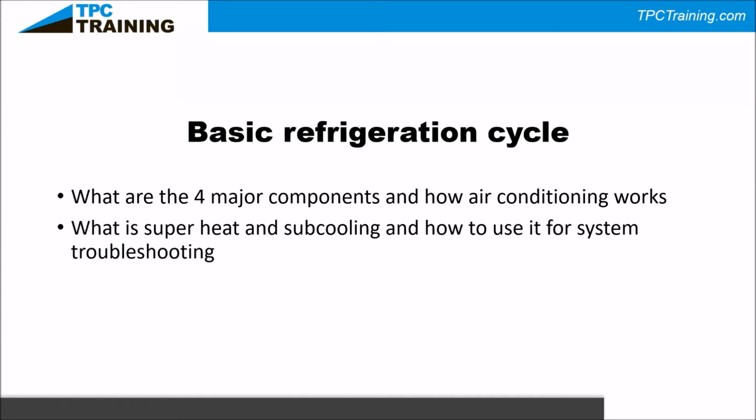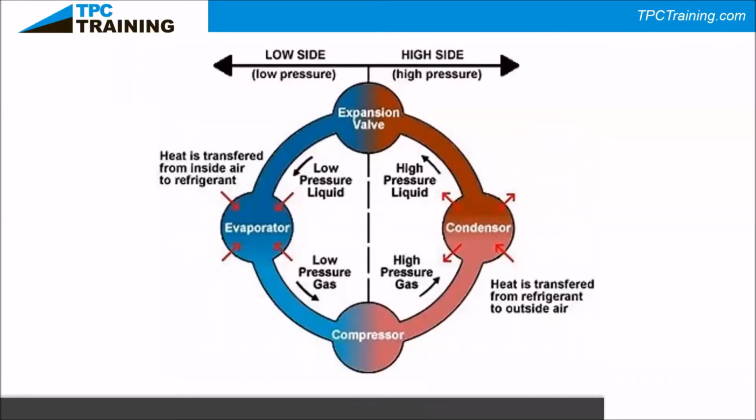And then we're going to get into a little bit about what is superheat and subcooling, and how superheat and subcooling are the aspects that are important to make sure that we are using them to properly troubleshoot our system. We have no way of knowing whether our system is fully charged or not without using superheat and subcooling as our examples. Here's a basic refrigeration cycle.